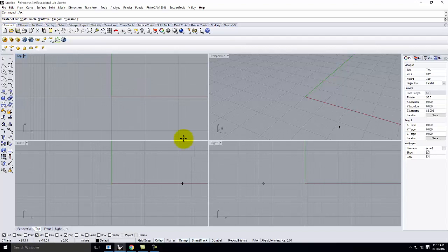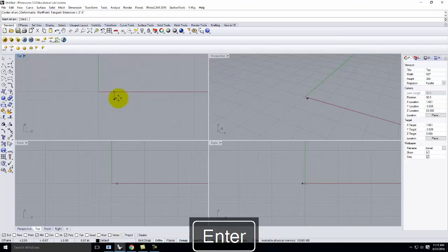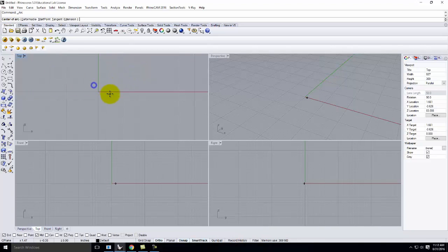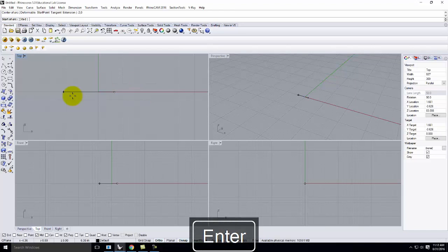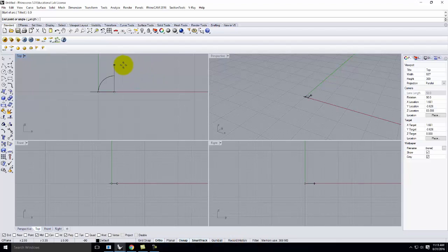So I'm going to go ahead and do an absolute coordinate of 2 inches, 0 inches, right? Which is going to put it 2 inches over from the origin. And I'm going to start there. Then I'm going to start my arc at 0, 0. Hold on a second. 2, 0. And we're going to go 0, 0 for the start of the arc. And the end of the arc is going to be right here at vertical. Okay, so I'll go ahead and draw that.